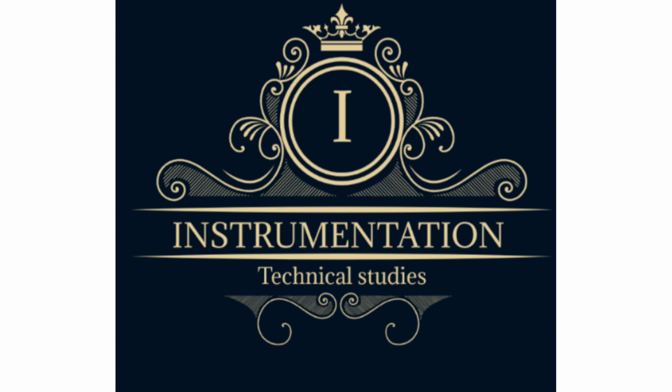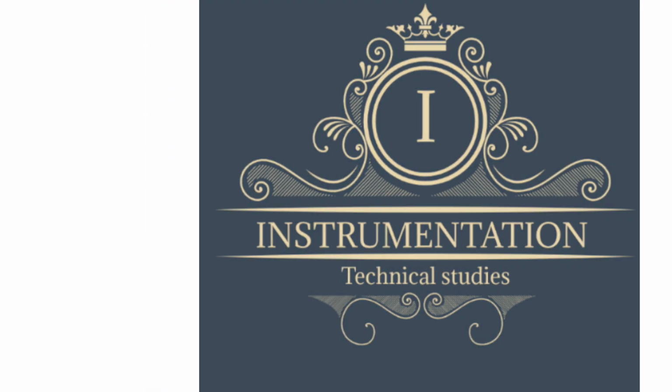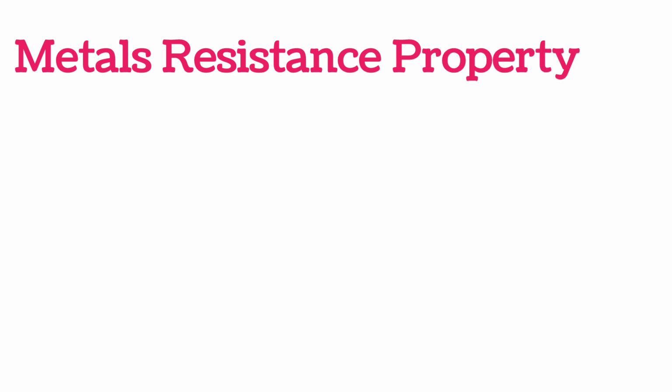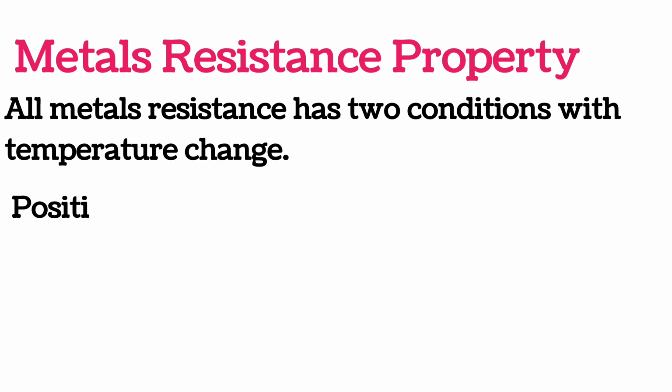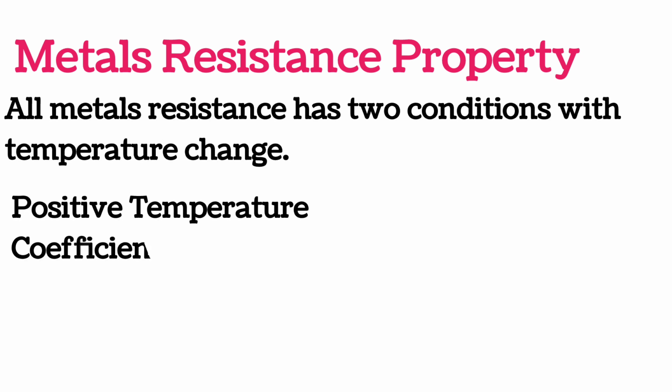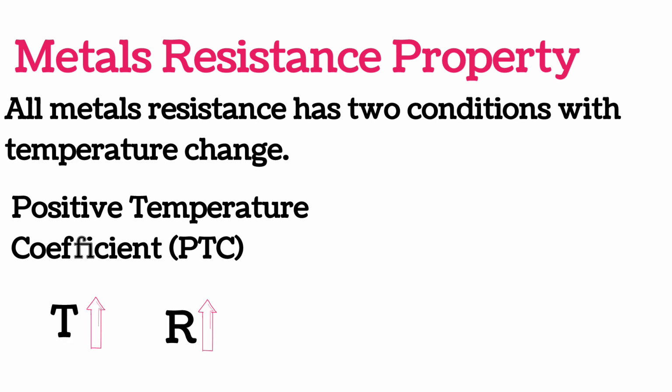Let's start our today's topic, RTD. Before going to RTD, let's discuss the metals' resistance property. All metals' resistance has two conditions with temperature change. The first one is positive temperature coefficient. In PTC, whenever the temperature increases, the resistance of metals also increases.